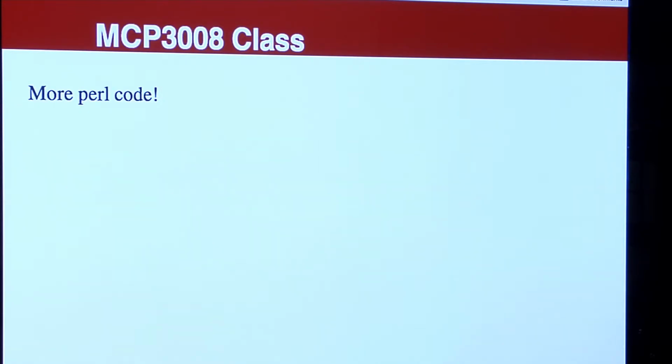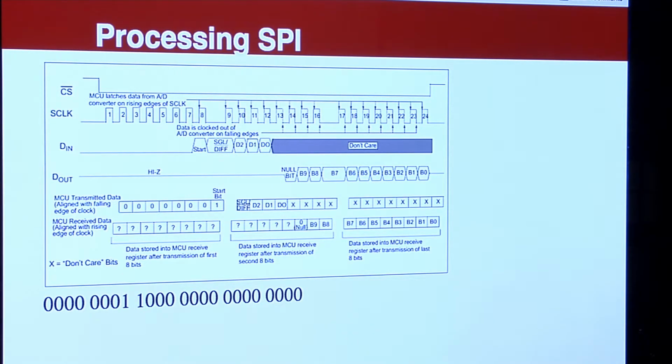So how was the clock referenced on the A2D converter? You have to have a clock reference. You do that by pulsing one of the pins. So your code, now we're doing it through hardware SPI. You can bit bang it. You could use any of the pins and do this.